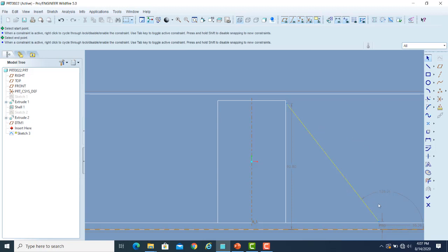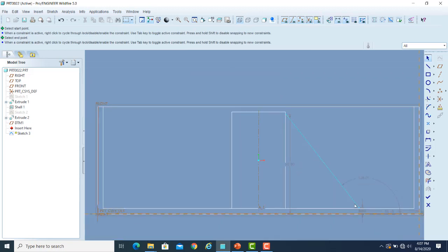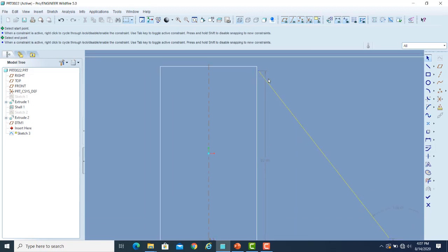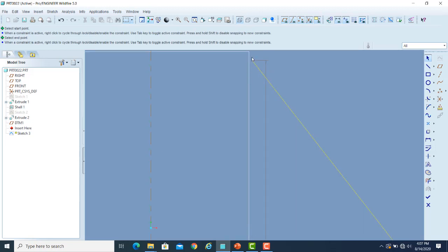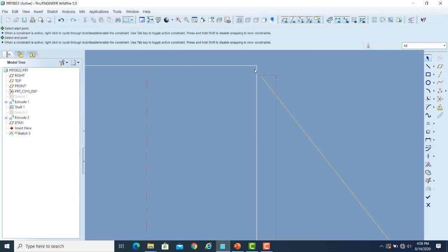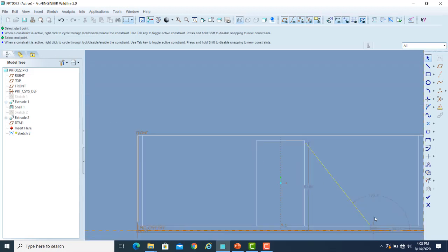And you can convert any curve to a solid region if the path that you will be following is a closed path, ठीक है ना. So यहाँ पे अगर आप देखें तो आपके पास open region है, ठीक है ना. तो you will not be able to convert that to rib feature. So you must have a closed region for ribs.